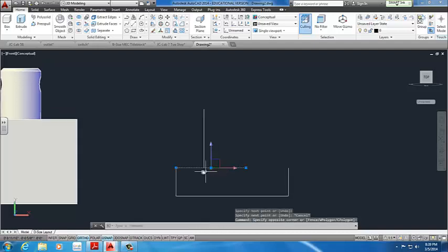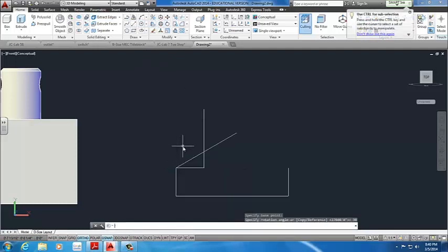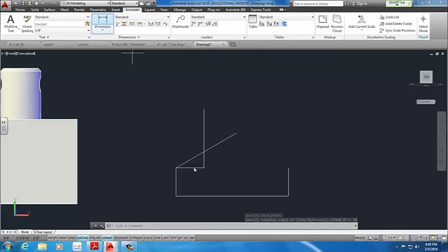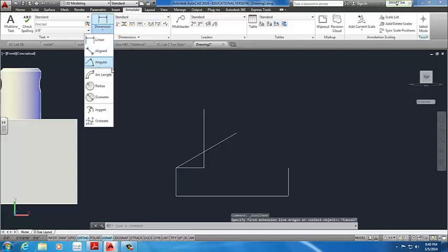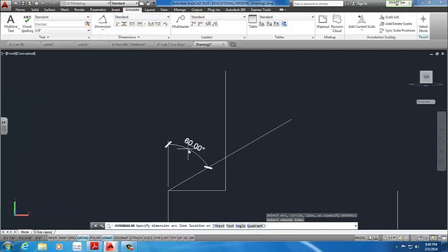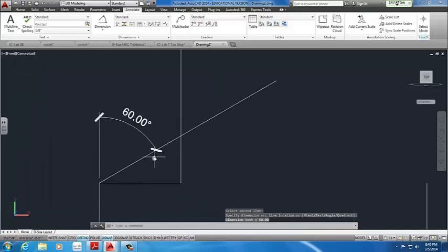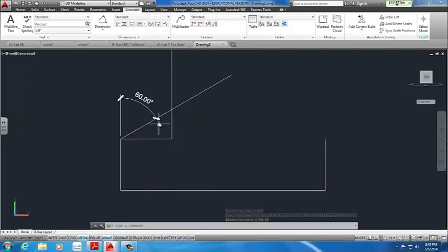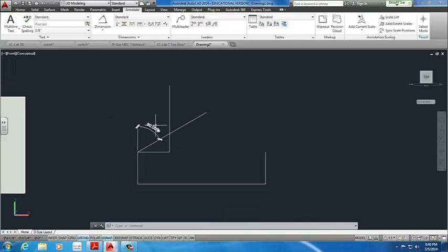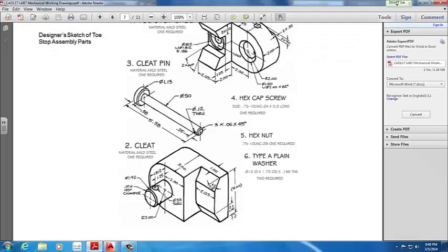and I'm going to rotate this around based from this point at 60 degrees. Right? No, 30 degrees. So we rotate this line 30 degrees. And that gives us our 60 total, right? That's what I'm thinking. So if I do the angular dimension, I have 60 degrees. And it should stop here because that is my 1 inch distance off from this line, which we see here. 1 inch off, and a 60 degrees where I got the 60 degrees.